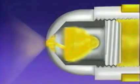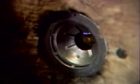Today's high-efficiency burners atomize number 2 fuel oil for efficient combustion. The oil is placed under pressure and forced through a finely machined nozzle to produce a controlled, mist-like spray of minute oil droplets. In this atomized state, the oil droplets are easily ignited with just a spark. Here, the spark is applied in an actual burner head using high pressure and an atomizing nozzle. A chain reaction occurs as droplets burn, then release their heat to ignite other droplets.